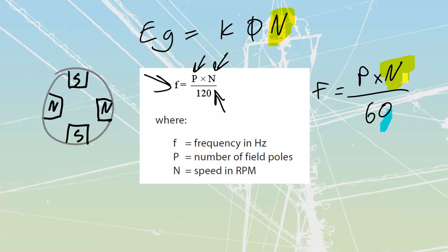It's going to adjust my voltage, which is a good thing because we do see voltage that sags away in a lot of cases, but it's also simultaneously going to adjust my frequency. And that's a really, really bad thing, because when frequency changes, we get a whole pile of other effects that are going to change. When frequency varies, all of our XLs and our XCs are also going to vary, and they're going to vary greatly, which means that total impedances of loads, all sorts of stuff goes crazy. We don't want to move off the 60 hertz system.